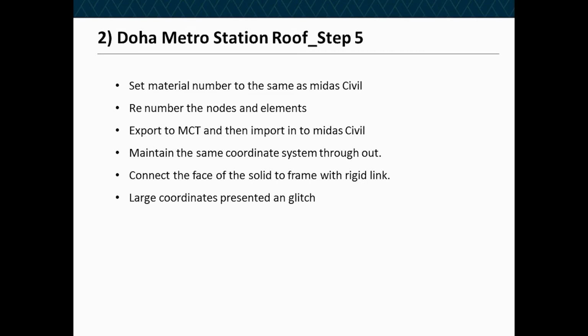Okay, it's also a very powerful tool if you want to generate that syntax within, say, Excel. You can automatically generate the syntax and import it, which is very useful for tendon data for post-tension bridges. Okay, so provided you keep the same coordinate system, you're absolutely fine.